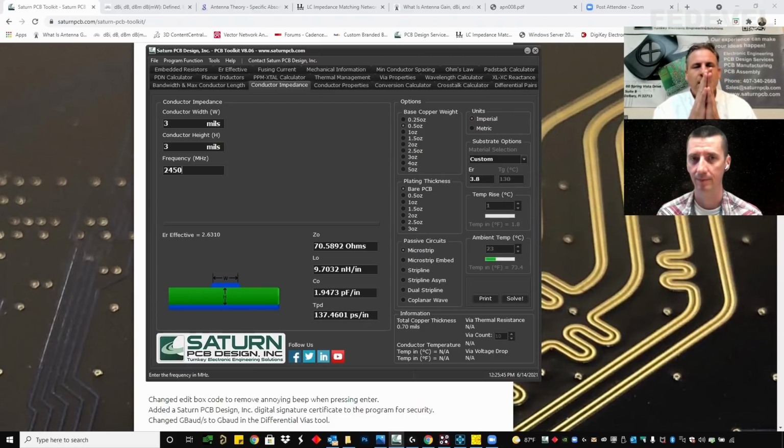You put the pre-pregs together, or the glue, and you melt them down, and things can change. Now, with the 2-layer boards, even though they don't press and heat up, there are still changes. I mean, it's just FR4. Do you know what is the difference between that material and the FR4 which you are using? Why will the other material not make so much difference?